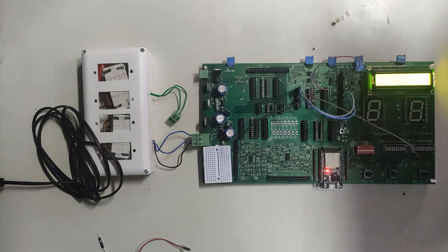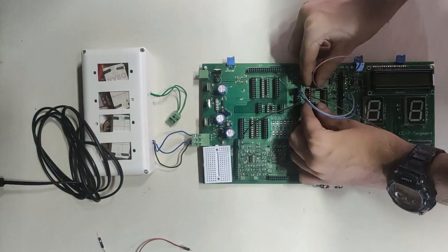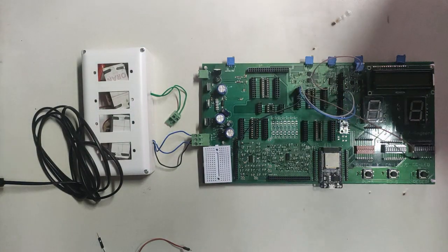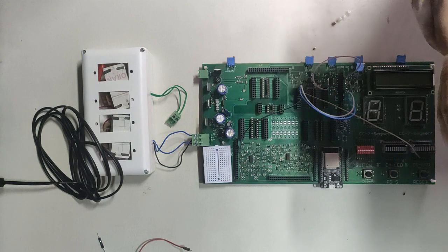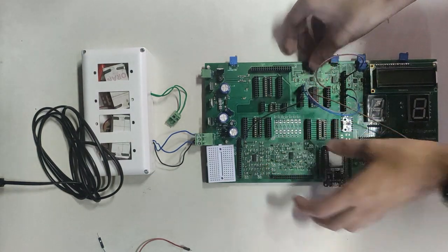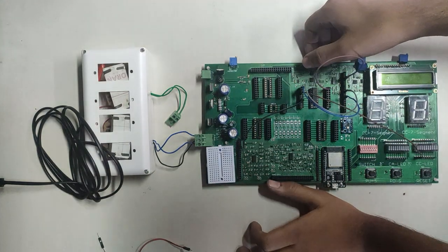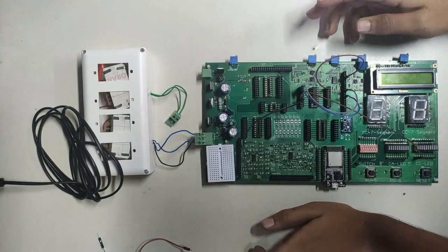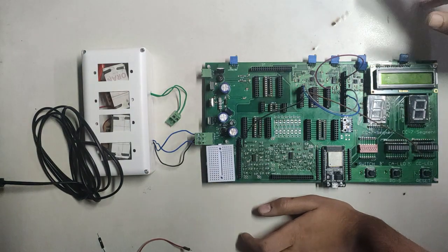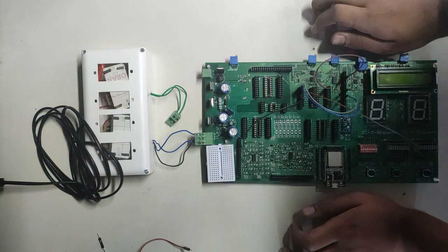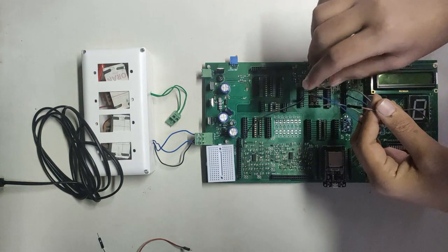After verifying the truth table of the NAND gate, we'll move on to the NOR gate. Now I'm going to mount the IC 7402, that is the NOR gate. After mounting the NOR gate, at first we'll look at the pin diagram. Pin number 14 and pin number 7 are again VCC and ground. But the IC 7402 has quite different connections, so make sure you look into the pin diagram very carefully.